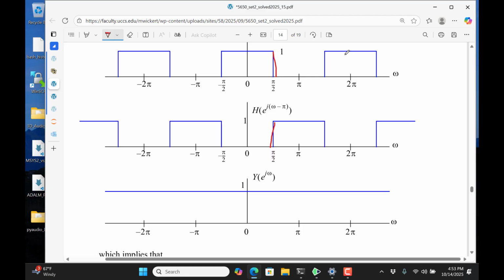It's not a quadrature mirror filter bank, but it's a similar type topology where you have this sort of thing going on. And they do this in coding theory right now. Speech and audio coding uses it too, where you will take subband coding, and the idea of subband coding is to try to save on the number of bits that have to be sent through the internet or into your home. So they will subband code the individual subbands with different numbers of bits to protect them from errors in the transmission, but they can get a net savings in